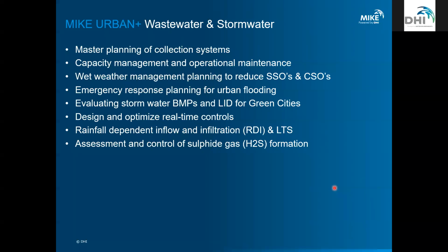And you still have the options to design and optimize the real-time controls, which is a very, very common feature that users are interested in. And it still has long-term simulations and RDI. And it also has the control with, a common problem is the buildup of sulfide gas in pipes. And so you can actually assess and control this now as well.